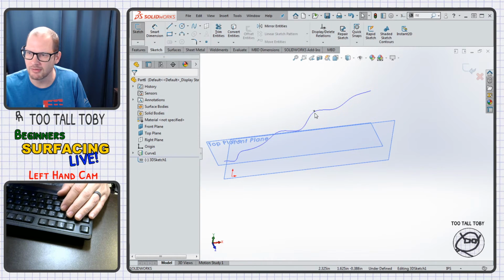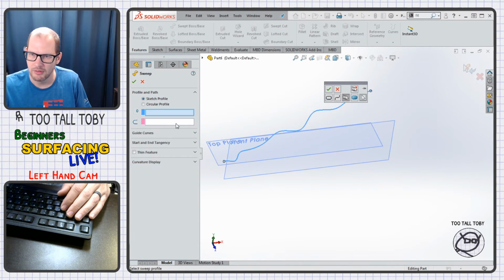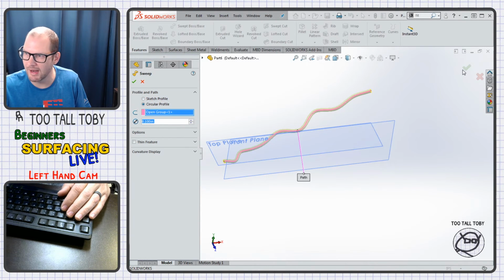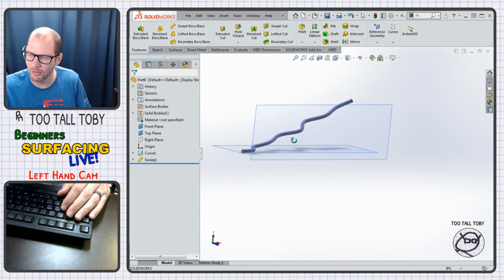So here what I would do is start a new 3D sketch. I would say I want that to be a sweep path. And then I would go into my sweep command, and I would say sweep a wire. This is what it reminds me of most often, a wire. Sweep a wire along that path. Look at that, 3D all the way through 3D space.